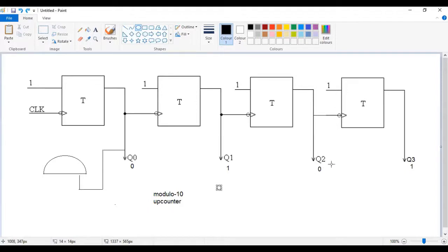You would also negate Q2, as you can see. So if you negate Q2, at this state, if it is 0, it becomes 1. In a way, you want to get all the states 1, and then this is going to produce a 1 at the output. So you would negate this one, and you would negate the next one as well. So this one is corresponding to Q2. This one is already high, so you would not negate it.